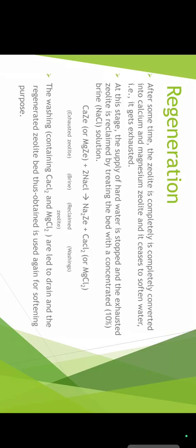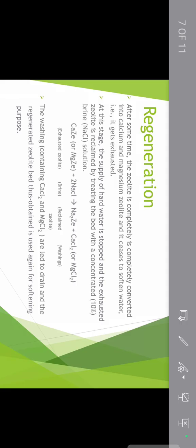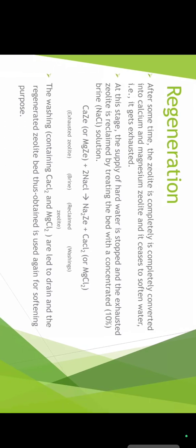Next, calcium chloride and magnesium chloride react with sodium zeolite to form calcium zeolite and magnesium zeolite, with the removal of sodium chloride. The softened water is enriched with a large amount of sodium salts, which do not cause any hardness but cannot be used in the boiler.